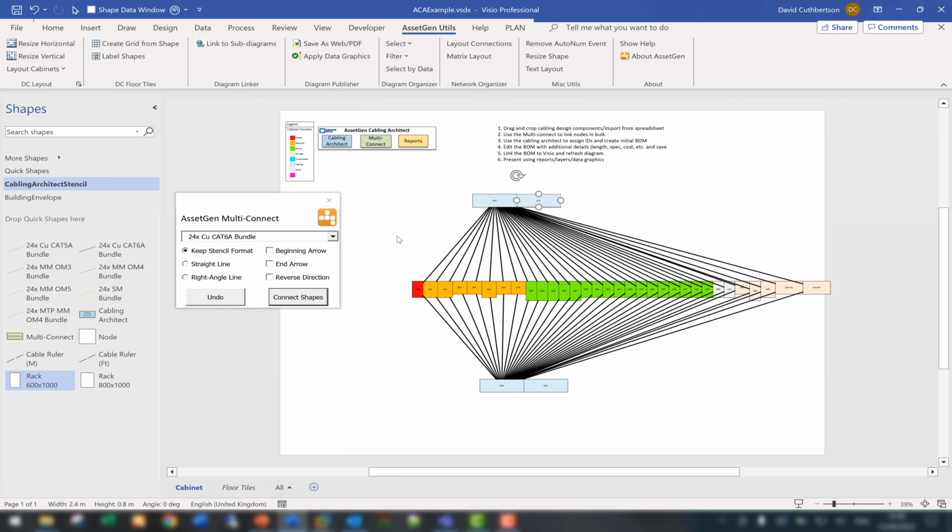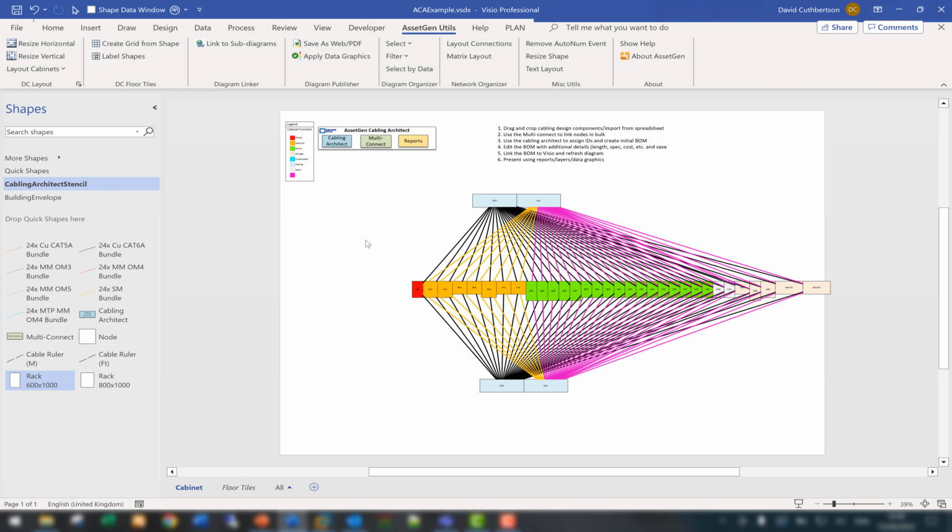Let's go to the fibre, and let's choose probably say OM4, but we're not going to connect that to anything really other than just the storage and the server racks. And the same on the other side. And then let's put in single mode to the network racks. So if I go to the fibre there, let's take all the network racks alone and connect them in. Of course, as you can see, you can override and do anything that you want.